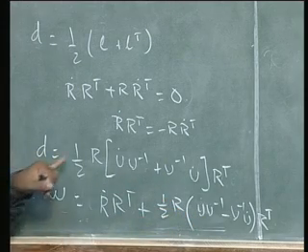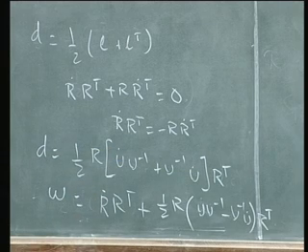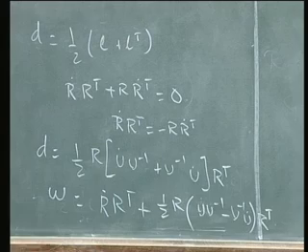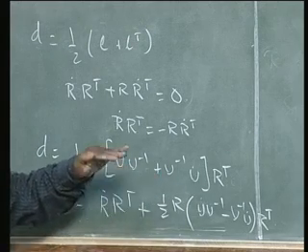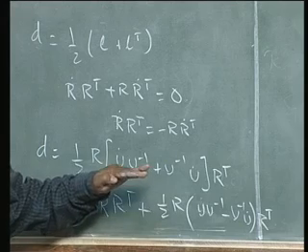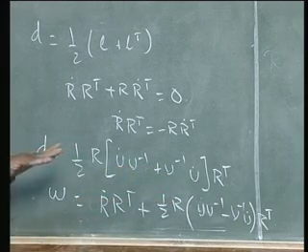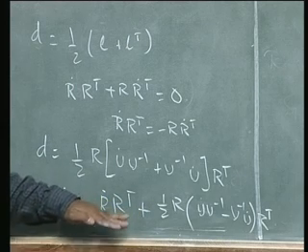So, D is not pure stretch, but also involves R and R transpose. So, both of them are not pure stretch, it's not stretch rate, it's not U dot. What I want to bring out by this is clearly that D is not just U dot, W is not R dot. This is a very important thing to remember.